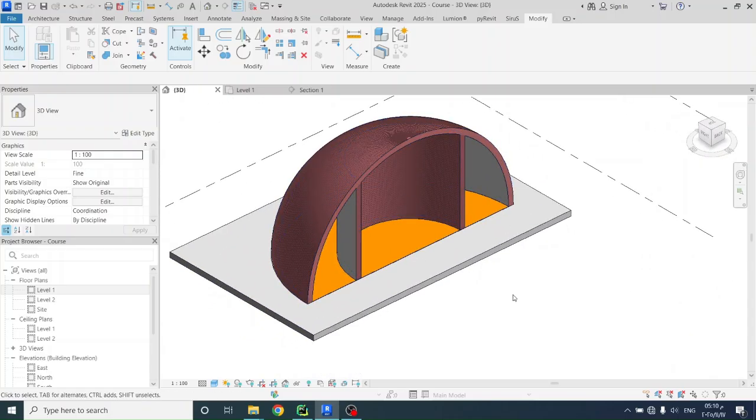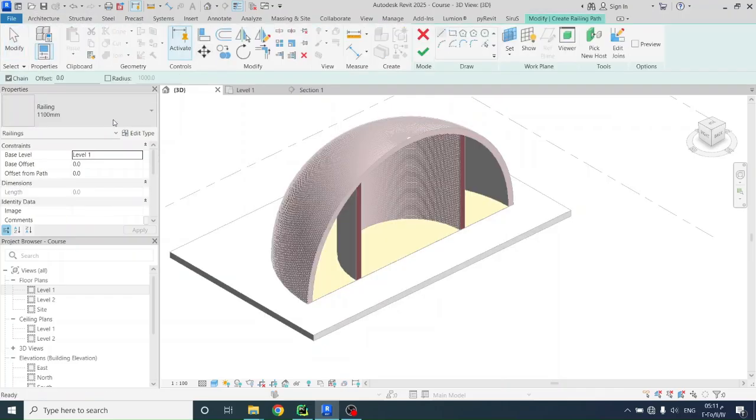Of course, there was a terrace that extends beyond the actual project. I'm not going to model it because modeling it is easy. You just have to extend the ground floor, the finished floor, outside the project's boundaries, and I covered it with a railing, a glass fill railing, the one that comes with Revit.